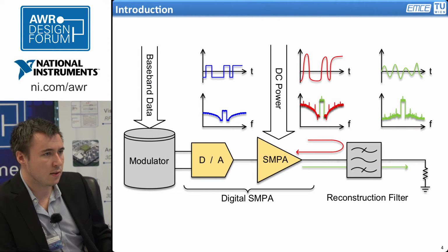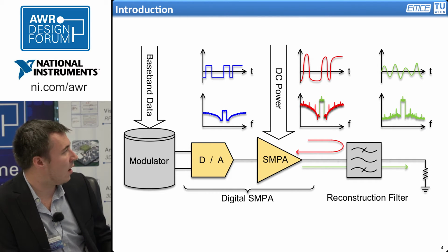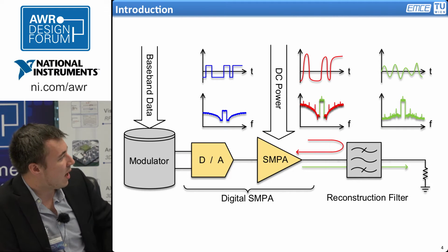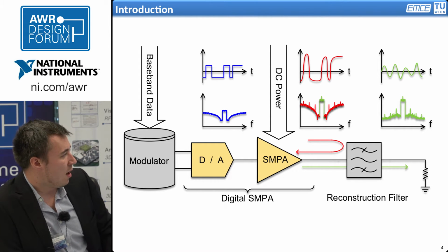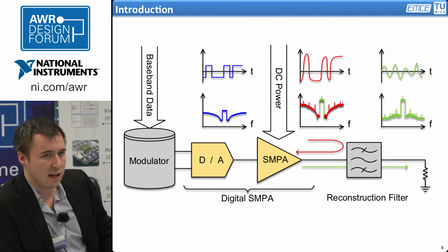To walk you through one of these exotic birds of all-digital RF transmitters, I want to present this chart, where on the left side you can see a modulator, which is basically a piece of software which takes in baseband data and performs a lot of fancy calculus and results in a very high rate stream of binary symbols, which is then played back using a very high speed single-bit DAC, and you end up with a binary waveform which in the center actually resembles the desired RF signal we want for our system.